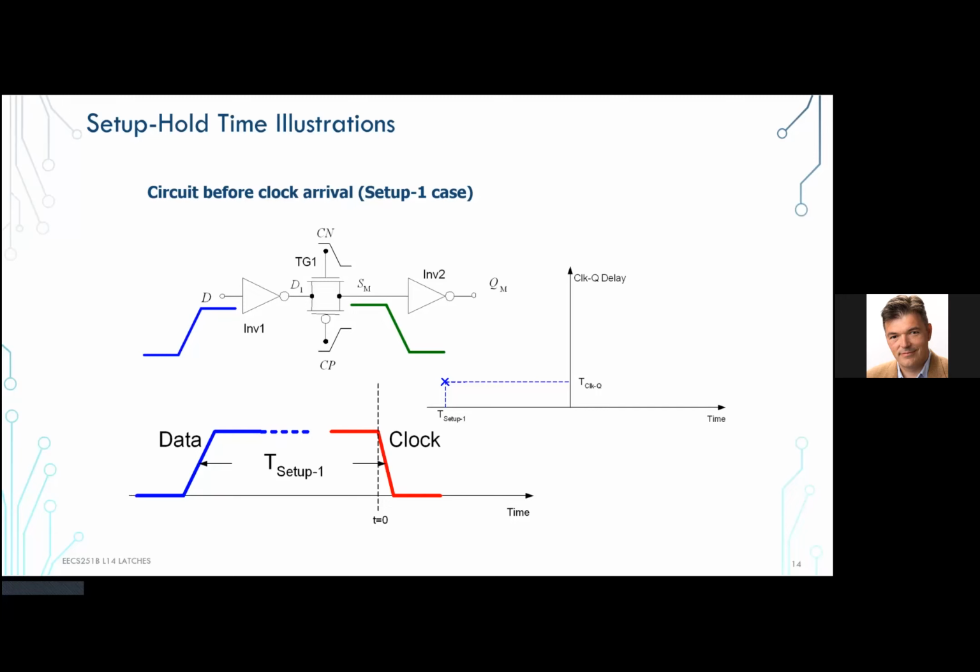the delay for a transmission gate latch as a function of data to clock separation. I could have plotted it like the previous slide, with clock or data to Q delay, and then I would have gotten something that drops down, gets flat, and goes up. But for now, let's just take a look at the D to Q delay as a function of D decreasing.